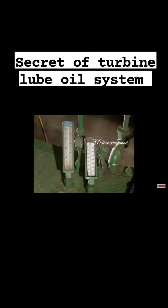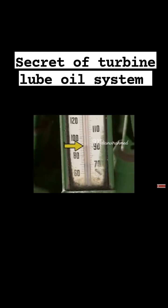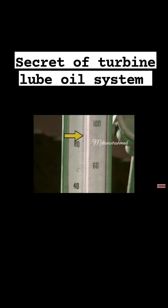It's also important to check bearing oil temperatures. This should be done at several locations around the turbine. Readings should be taken at the inlet and the outlet of the cooler to make sure that the cooler is operating properly.